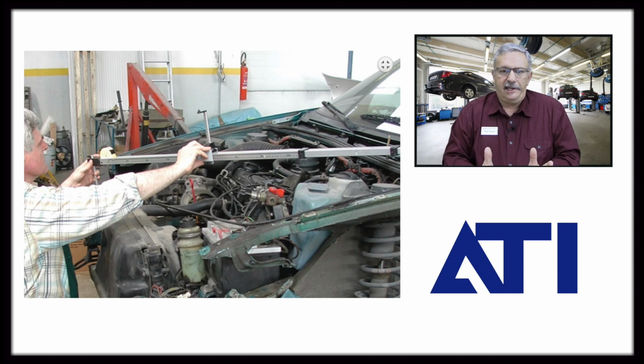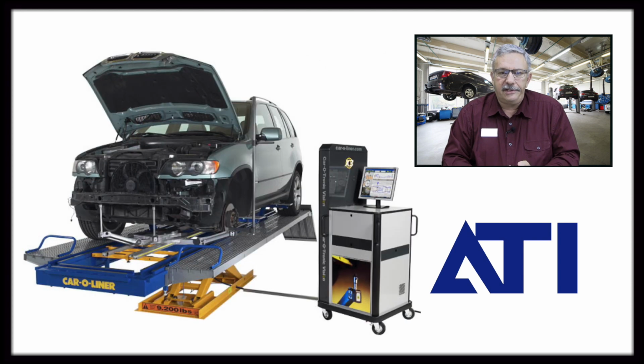What we typically see is a three-dimensional measuring system. The one that we see the most right now, and the one that you have the visual of, is the Car-O-Liner system, and this is called a Faro arm. All you do is move it to specific points on the vehicle, hit the button, and it registers what the measurements are.